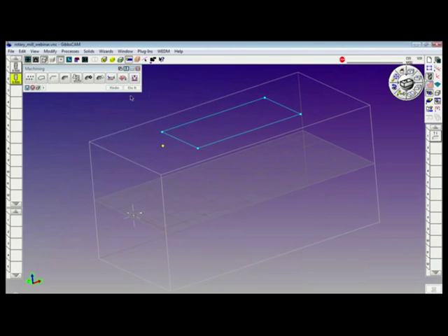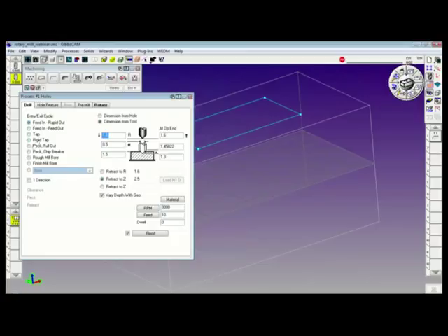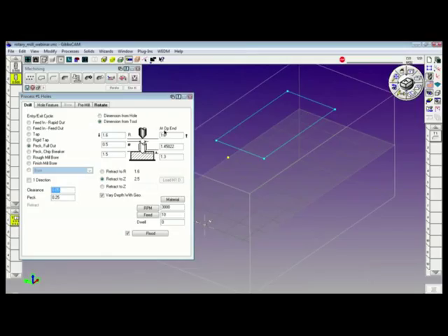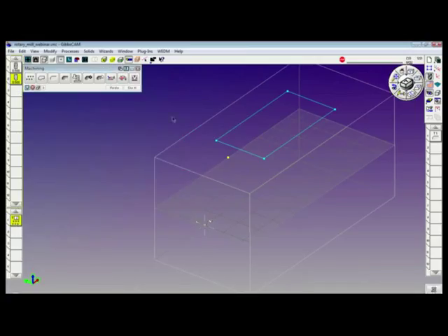And bring the tool down, the drilling process. We're going to do a peck with a full out. Notice that the system has retained the information for the rapid approach and retract at 1.6. Stock is at 1.5. And I'm going to take the shoulder of the drill all the way to 0. So we get some intersecting holes here. Speeds and feeds look okay. I'll close the dialog.